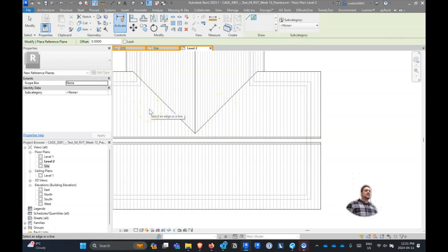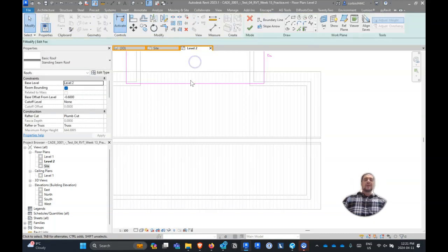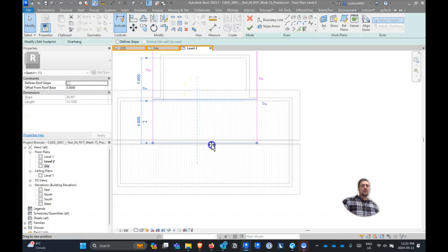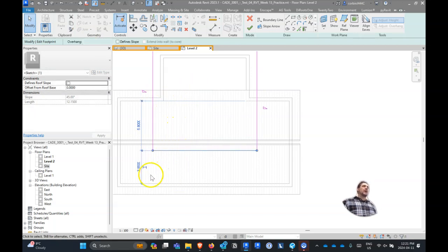If you don't see a line where they intersect, you could simply join them. Another way I would go about this process is to take the roof I want to intersect and oversize it, making it artificially larger by whatever amount I want, and click the check mark.